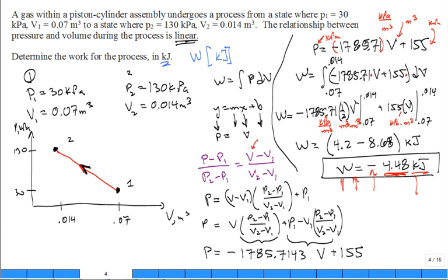All right, you had a question? What was the negative again? Why is it negative? Good question, because who's doing the work? Is the trapped gas receiving work by being compressed from the surroundings? Usually the face of the piston is a part of the surroundings and it's compressing the gas. So the system is getting energy transferred into it via a work transfer by being compressed, and it's not going out. If W is positive, the traditional sign convention, it's work out. If work is negative, it's work in. The system's receiving that energy transfer.